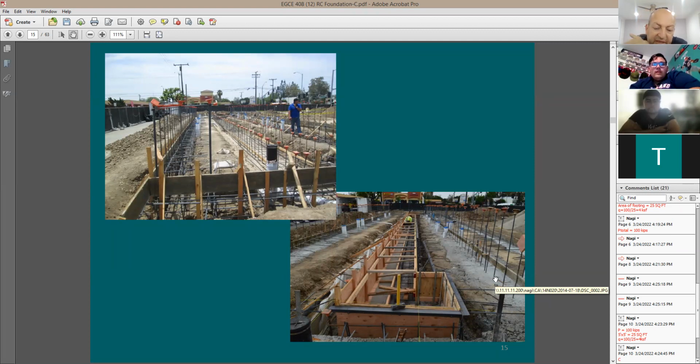This is not the case in beams and columns. In beams and columns, they are gonna be exposed, and you cannot play with the column size. You cannot make this column larger than the size I put in my drawings. You cannot do it this way for architectural reasons. Same thing for the elevated slab. You cannot make it higher or lower because you have a given building height that you need to maintain. But in foundation, everything here is going to be covered with soil, right? So it's okay to make it a little bit larger.